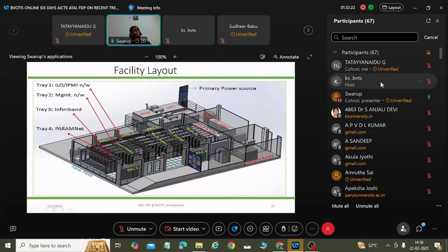Okay, and the UPS output is here, and this output is connecting to each of the racks. And the ACs are never connected on a UPS, because the ACs are variable loads, and variable loads are not connected onto the UPS. They'll always be connected on the raw side.